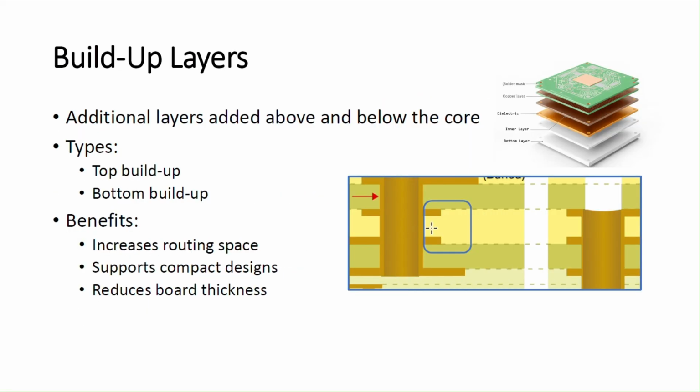Like here you saw, right? One layer is here and another layer is here. All are connected to maybe a 5-volt supply. But how will you connect? You need some kind of a bridge between all these layers, which will connect them together. Here this copper plated hole will help you to connect all these four layers to a single net.